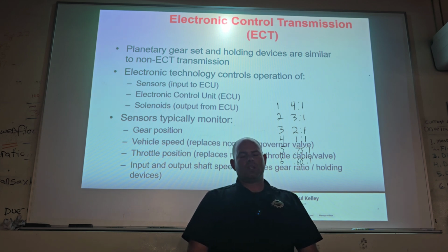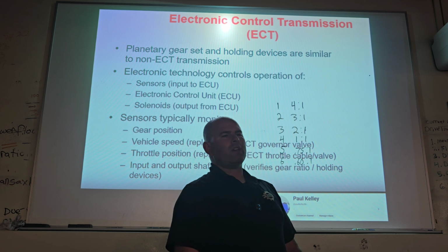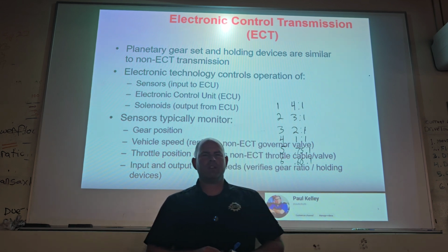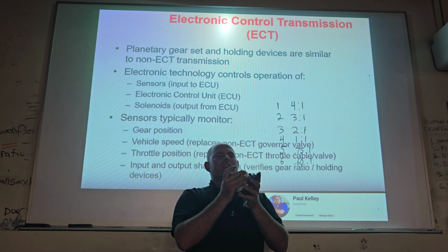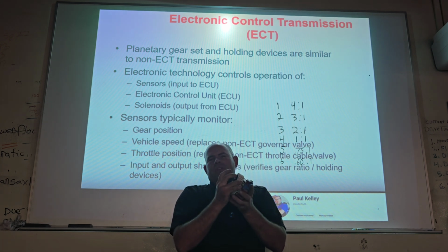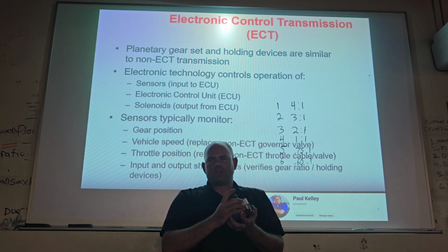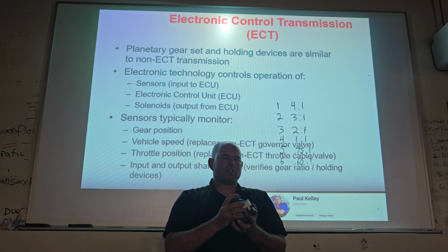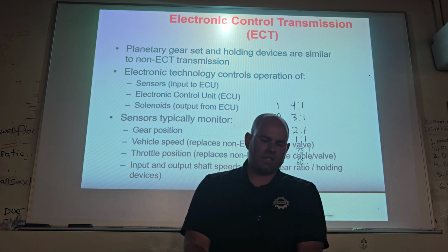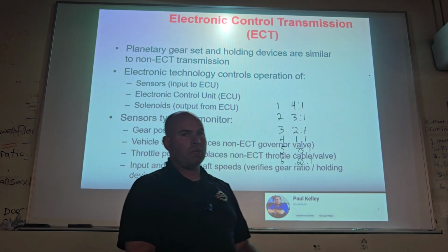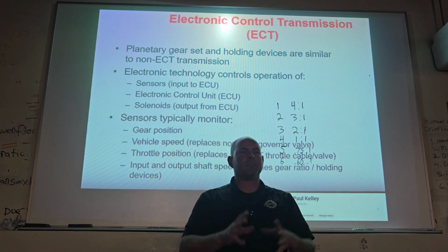It's like, does that mean someone put the wrong 5th gear parts in there? Or the wrong 1st gear parts in there, I mean? You understand, this is every gear. There is no first, there's no fourth, there's just hold something and turn something and have something be turned. Make sense? So if in first gear, you're getting a 5-to-1 gear ratio, but in second gear, you're back to your 3-to-1 ratio, that would mean in first gear, some holding component is slipping.